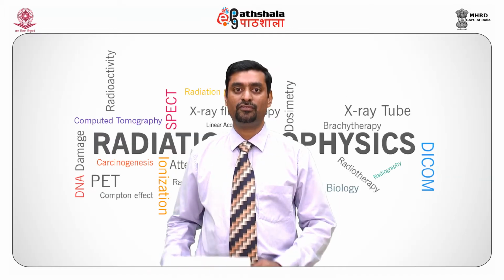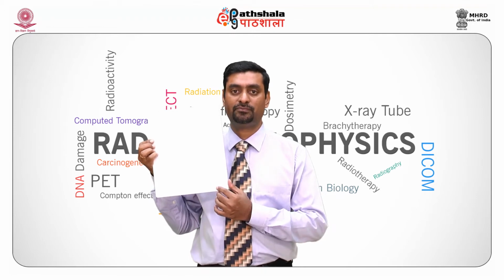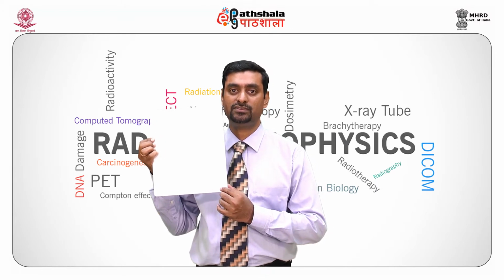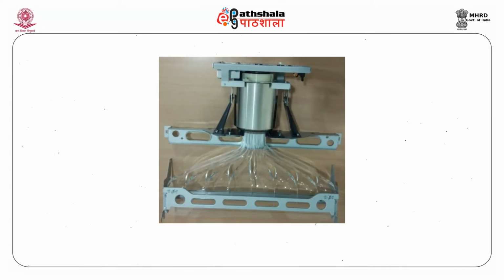When the laser source falls onto this IP plate, the europium 3+, which was activated because of the X-ray image formation, falls down into europium 2+ by releasing an energy of about 3 electron volts, which is nothing but a light photon. The photostimulable light that is formed because of the laser is channeled into a photomultiplier tube through this optical coupling, what you see here. The photomultiplier tube converts light into photoelectrons. These photoelectrons are accelerated and amplified through a series of diodes within the photomultiplier tube.